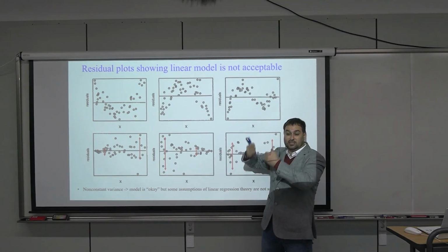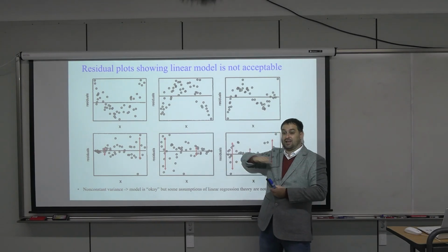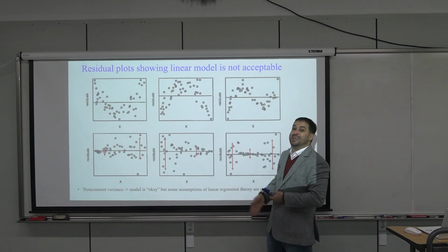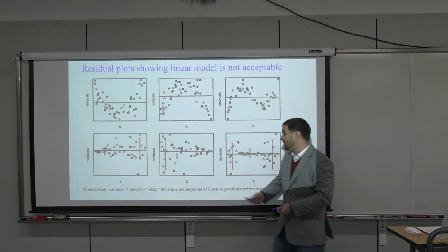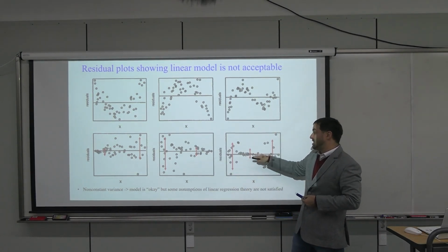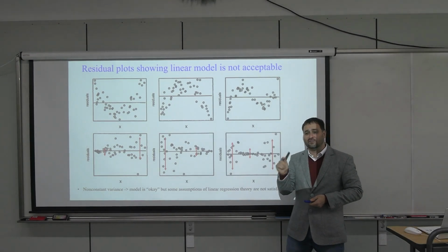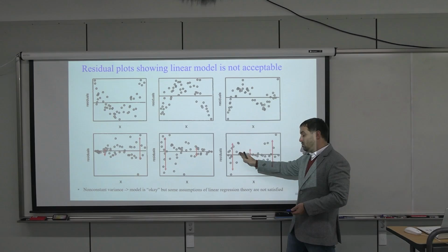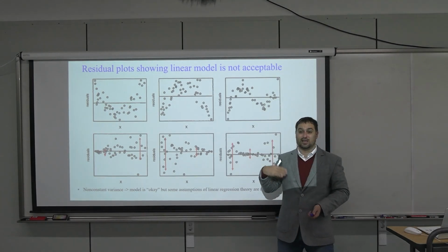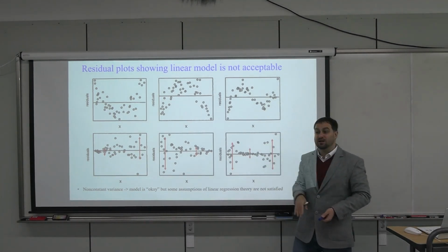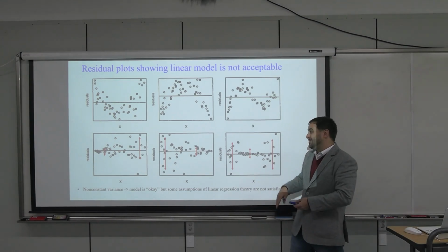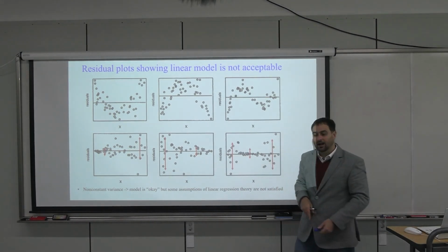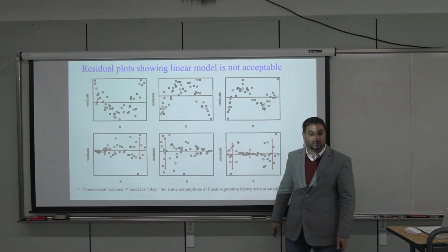Then you get to a transition region where you oscillate back and forth between turbulent and laminar flow, so you have a region of instability. This might be telling you about the underlying physics of your problem. That's the point I'm trying to make. With the fluid flow, then you're turbulent, and at some point you'll start cavitating, which will be oscillatory. So it could also tell you that your underlying physics might be unstable in these regions, okay?